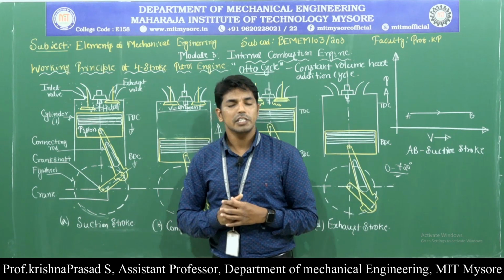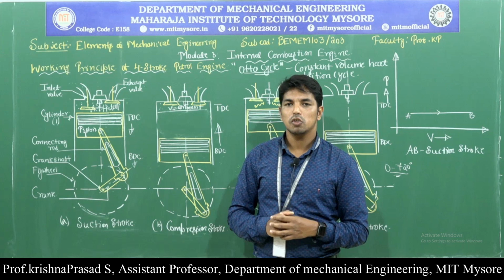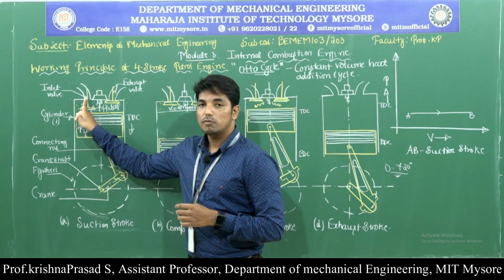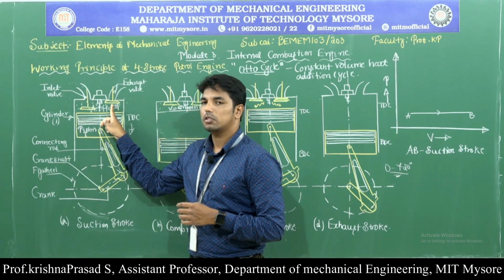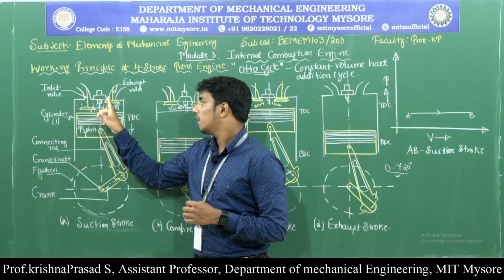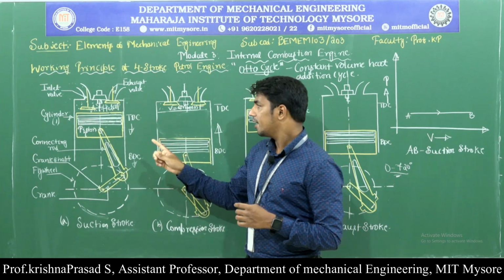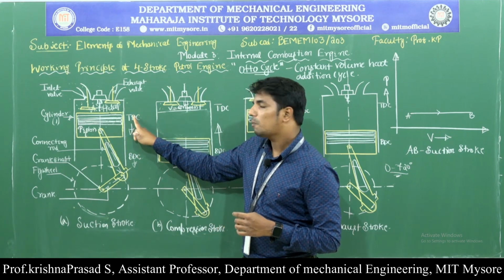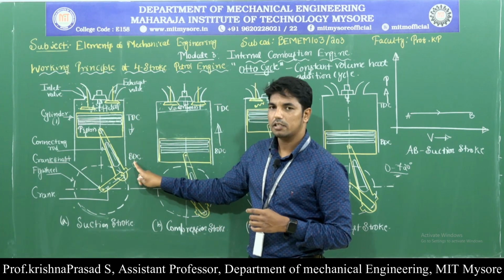Now we will come to the first stroke of the engine, called the suction stroke. What are the things we need to remember during the suction stroke? That is very important. During the suction stroke, the inlet valve is open and the exhaust valve is closed. And during the suction stroke, the piston moves from top dead center to bottom dead center.